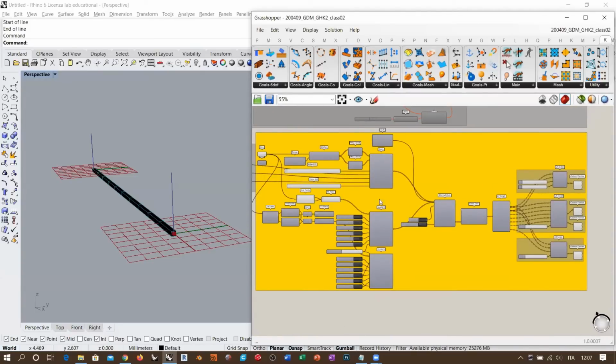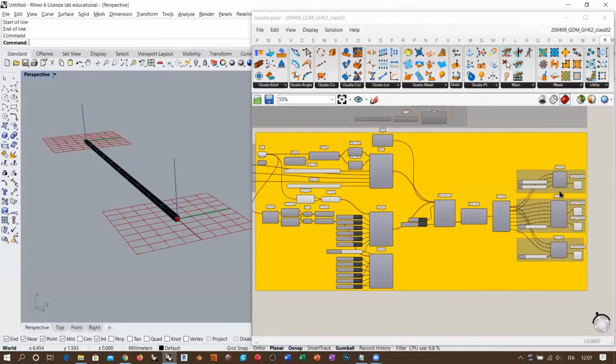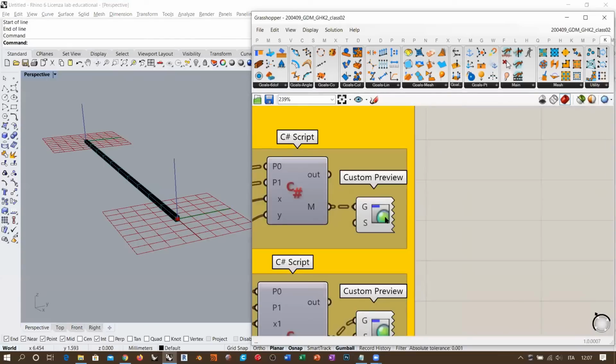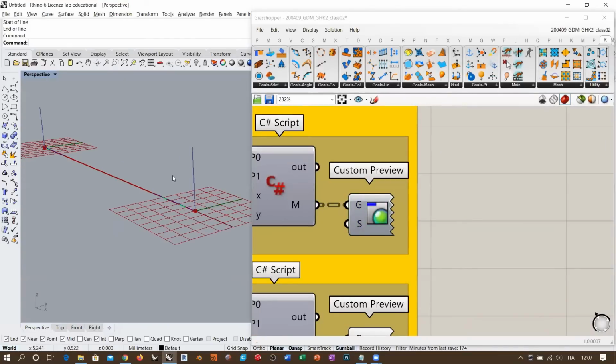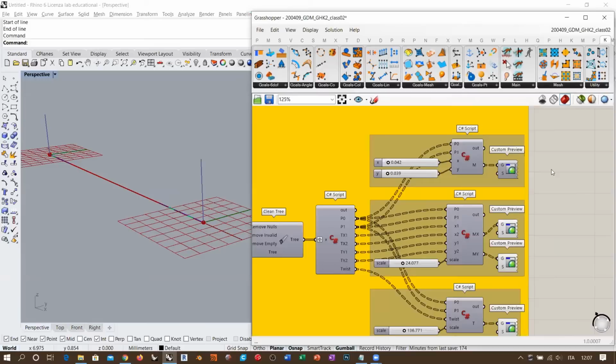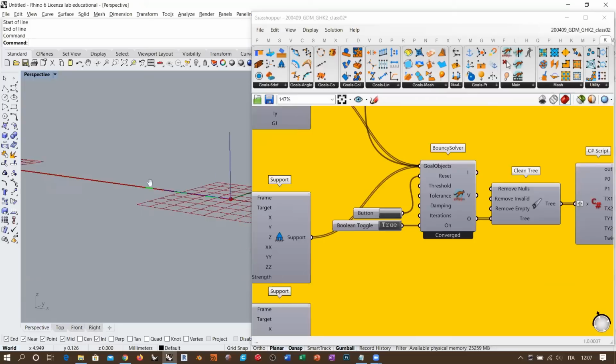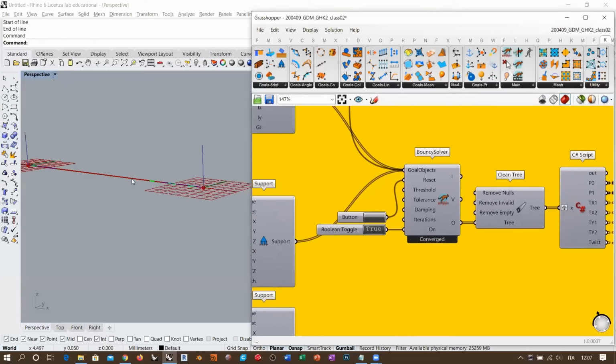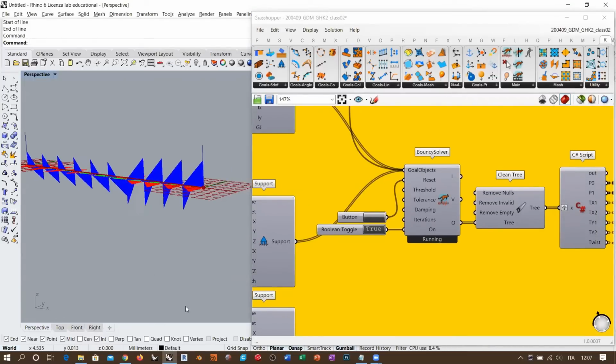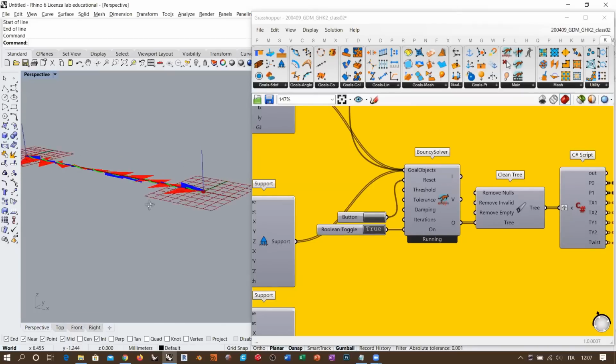But anyway, these are just variables here. The importance here is the stress. So eventually we can also turn off the preview of the geometric element in order to concentrate for a while on the stress representation, and we have the possibility to drag the elements and see how stress comes out. This also allows to detect if we have some torsion.